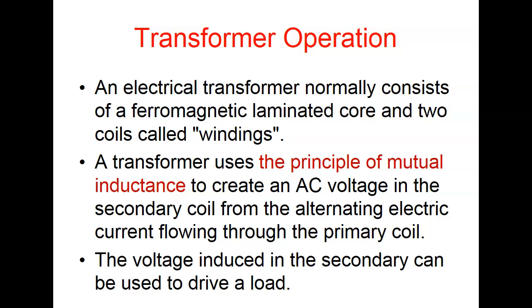And what's nice is that the secondary is totally isolated from the primary. So this is why out there on your power lines, if you've got a transformer, they have to run a ground down from that transformer to reestablish ground. Because if they didn't, the ground on this side wouldn't necessarily have to be the ground on that side, right? Or the common on the left would not have to be the common on the right. So a lot of the power that they transmit, they use a delta transmission, and it's not even referenced to ground.